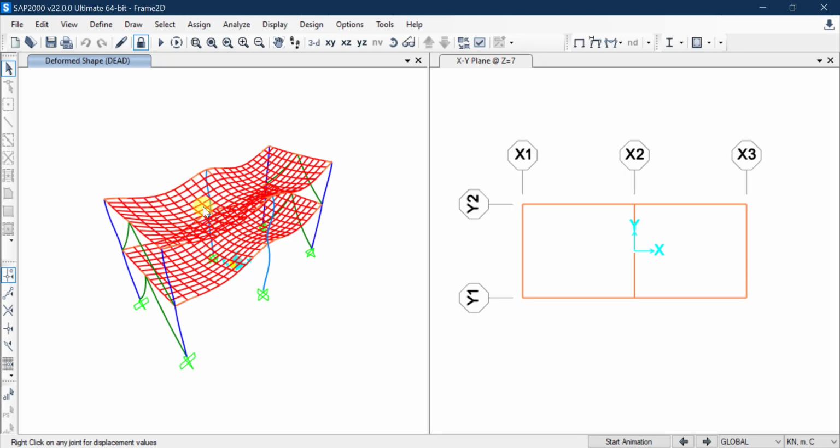So now you can see here the 12 by 10 mesh size. Okay, and you can play with that. As we said, you can make the mesh more coarse or more refined and see how this will affect the results. Here, since we did 12 by 10, it seems like a very adequate mesh, and the deflections look smooth everywhere.